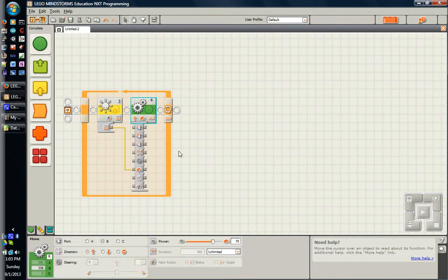Now let's think about what this will do for a minute, okay? This will take the light intensity and make the motor spin that fast. But the intensity of the light sensor can range from 0 to 100. But we want our motor power to range from 0 to 50, because I just want to cap it at 50% power. Now, there's two ways that we can do this.